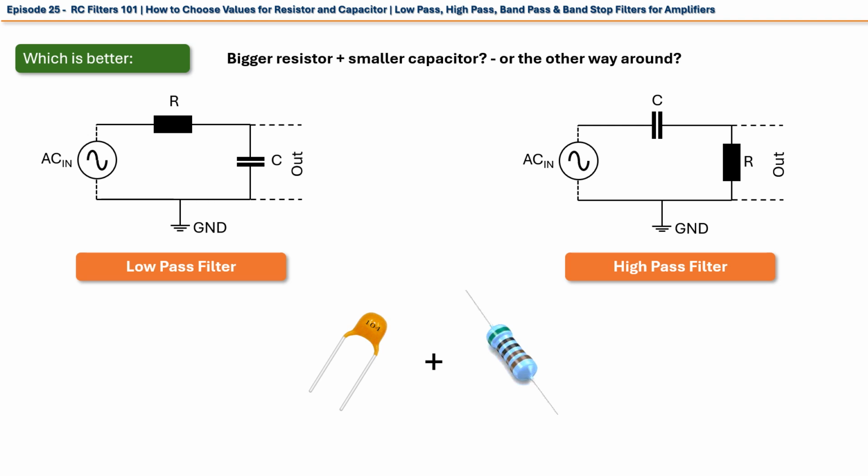So, logic dictates that you will get a better result by using a larger capacitor, with far less discrepancy in its capacitance from the declared value, and a smaller resistor that already has a smaller discrepancy in declared resistance. Furthermore, variable resistors are way cheaper than variable capacitors, so if money is a factor, then the choice is clear and obvious. Our recommendation: use whatever you have on hand, it will work.